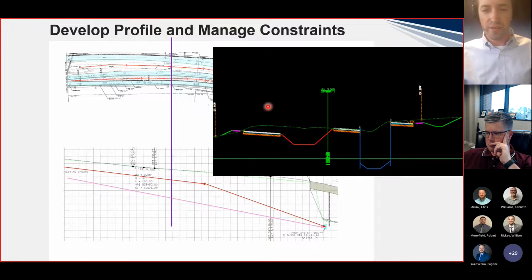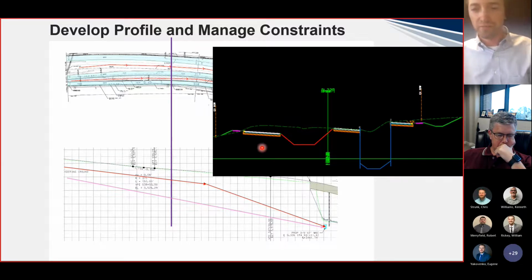And you see that now we have nice reasonable side slopes, and this is also ideal in the drainage world. We got a nice flat bottom ditch that's going to have plenty of capacity. We almost never have to worry about a ditch like this not having enough capacity unless we have some major stream flowing into it. We're going to do the same thing for this ditch over here.